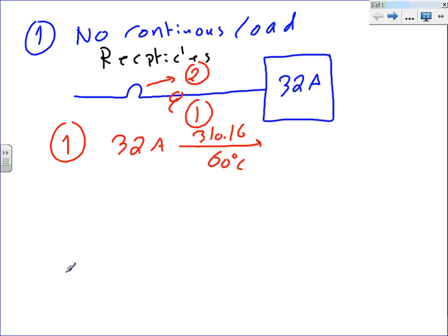So this is number 8 AWG. How many conductors depends on the equipment. Since we are commercial, let's use a 3-phase. Let's say that was a 3-phase. So how many conductors in this case? It's most likely 3 conductors, number 8.